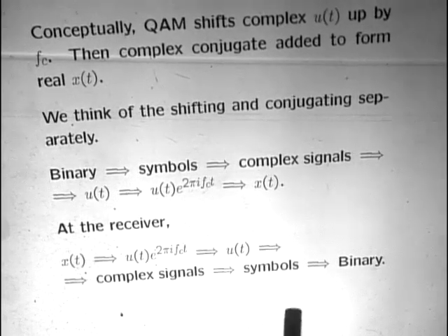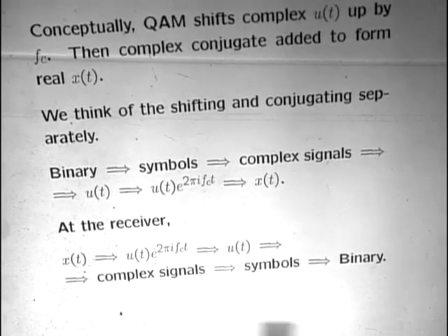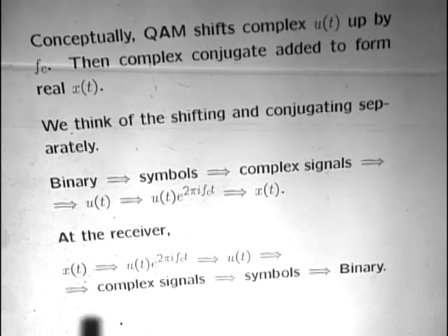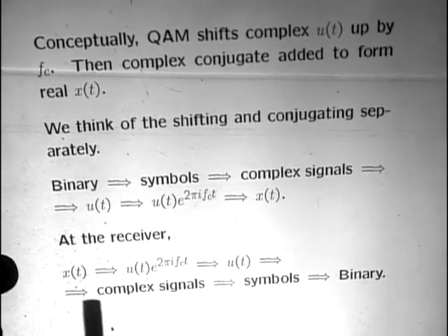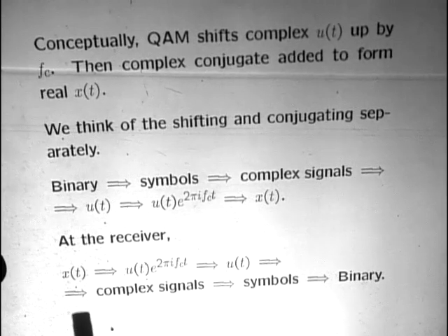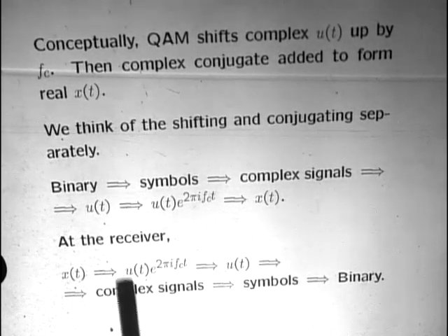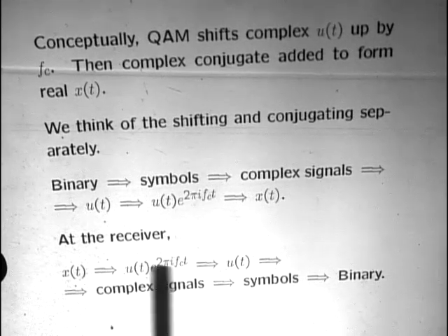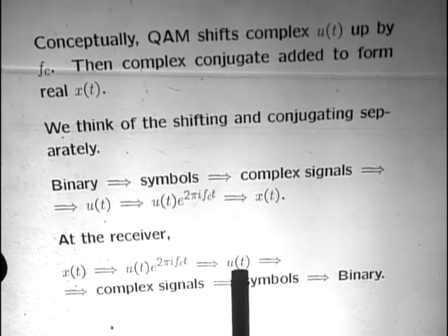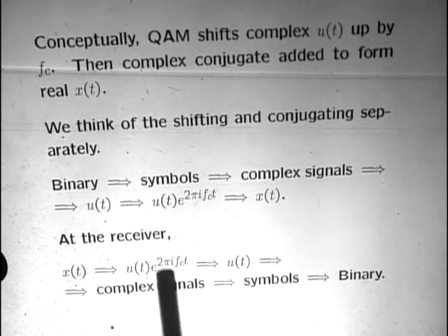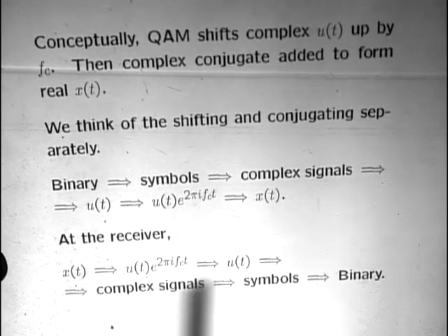As always, we do just the opposite. Namely, one of the reasons for wanting to think about this way is we want to use this layering idea. And the layering idea says you start out with a received waveform x of t, and later on we'll have to add the noise to it. You go from there to the positive frequency part. You go from the positive frequency part, you shift it down to u of t. How we get from here to there, I'll explain in a minute. You go from here down to baseband again.